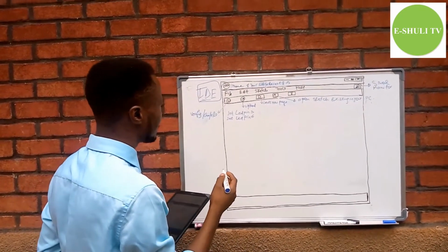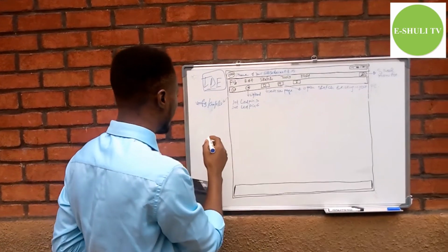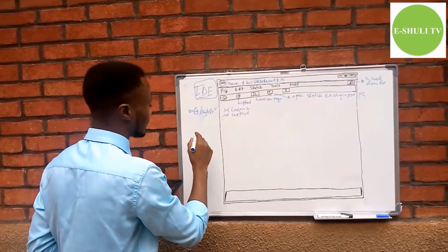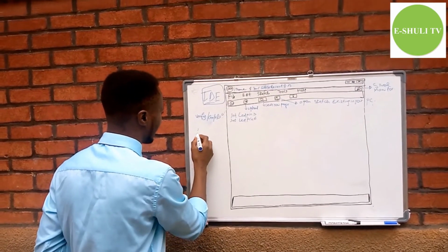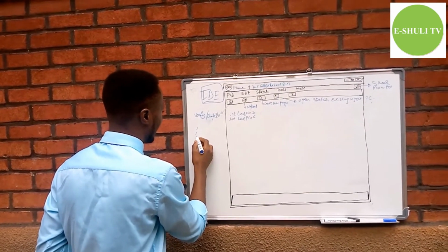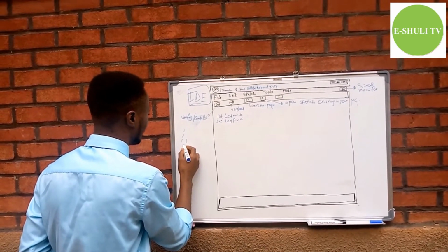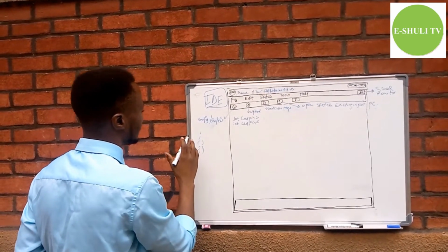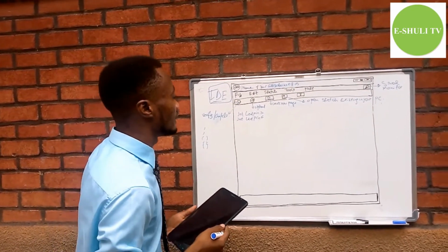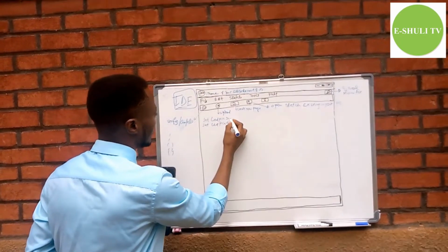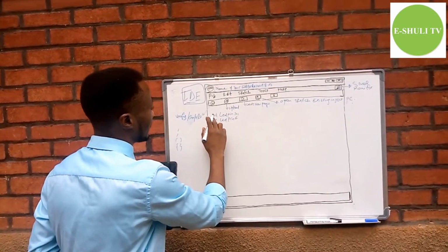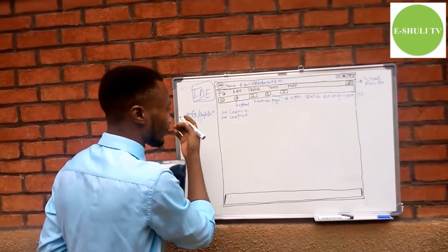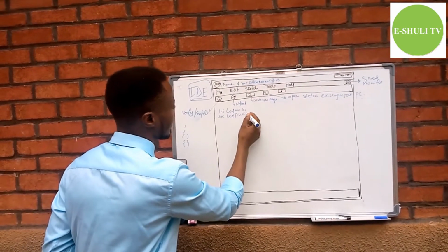Then there are some important symbols that you must respect while building the sketch in Arduino: semicolons, commas, brackets, and curly brackets. Those are the most useful while building a sketch in Arduino. After you write int red pin 3, you have to put a semicolon. Then int red pin 6, semicolon again.